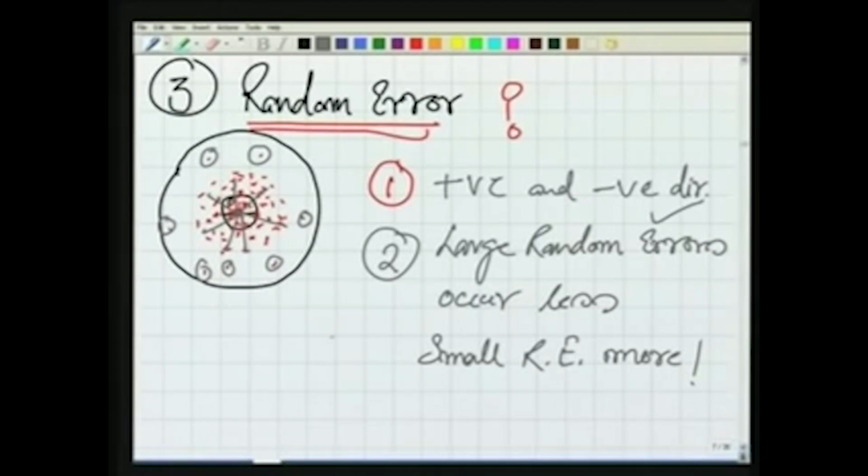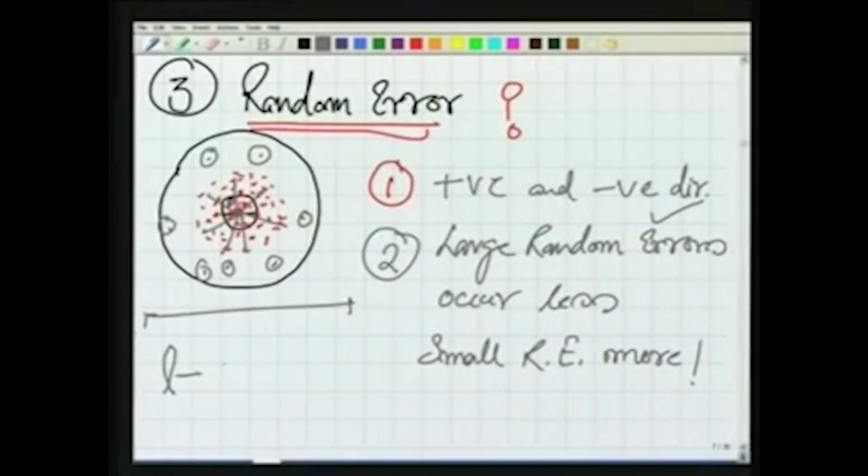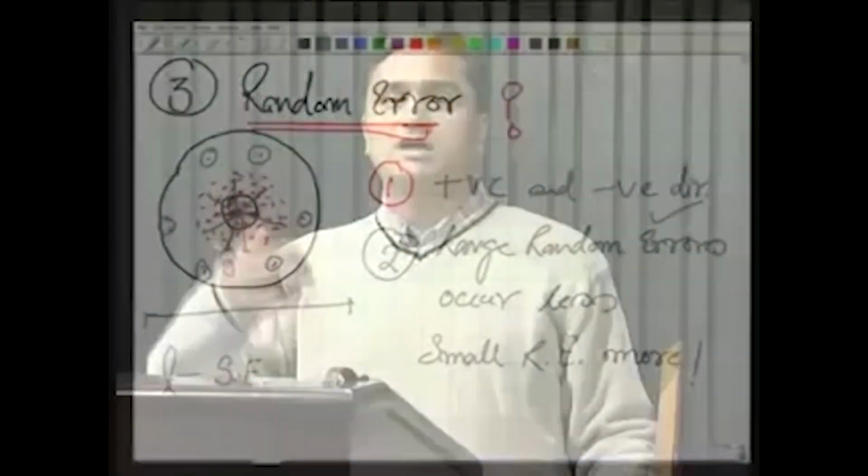But this is one error. Let us say your observation is L, for a length which you measured. You eliminate blunders or mistakes, fine. Then you eliminate the systematic error, SE, from your observation. You know the model of how this error has occurred, so you eliminate it also.